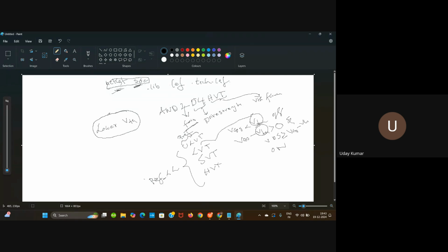So the electrons that are to be involved in the source to drain flow can sometimes go sideways. So in the lower VTH, ULVT is ultra low VTH. That's very, very low VTH. Okay, so if you take this, the delay trend will be increasing.